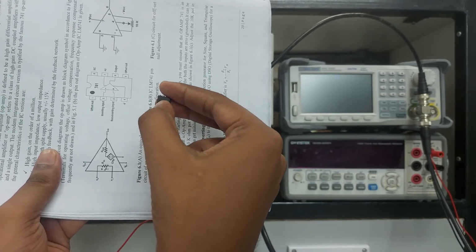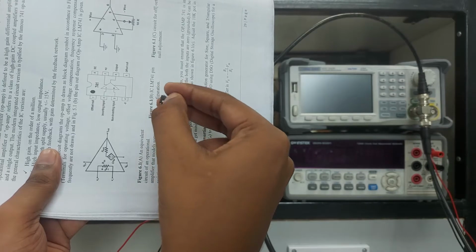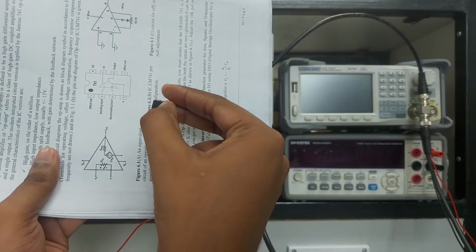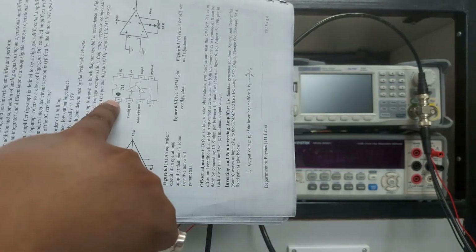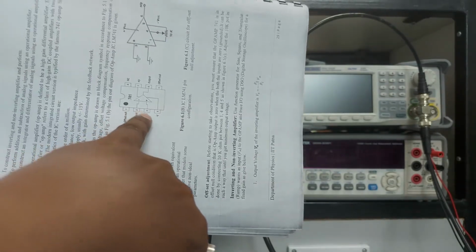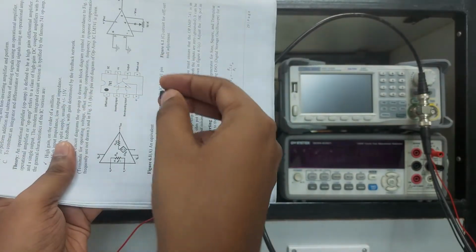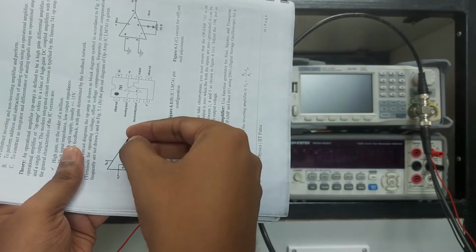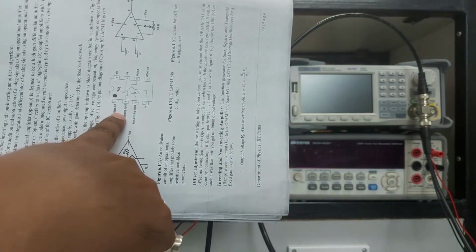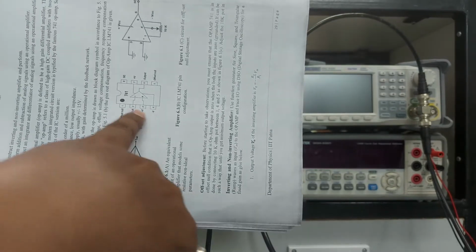So in front of 1, 8 will be, in front of 2, 7 will be, in front of 3 obviously 6, and in front of 4 there will be 5. So here you can see there is pin number 1, 2, 3, 4, now 5, 6, 7 and 8. Now we'll identify what is pin number 1, what is pin number 2, what is pin number 3, and so on. So pin number 1 is the offset pin, pin number 2 is the inverting input,